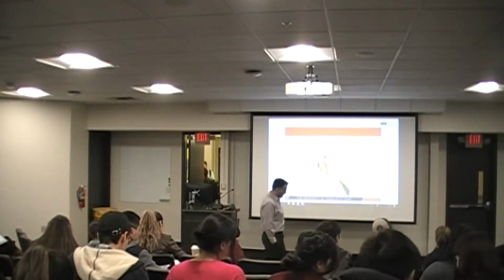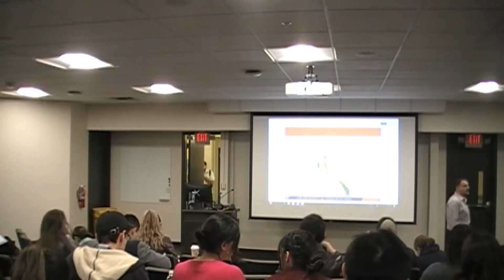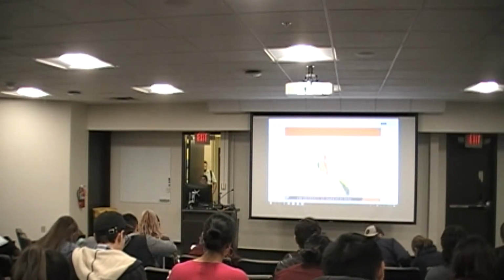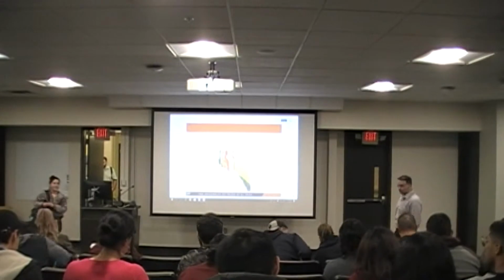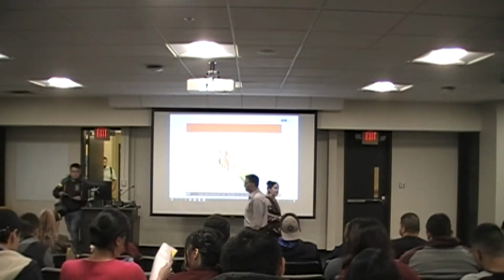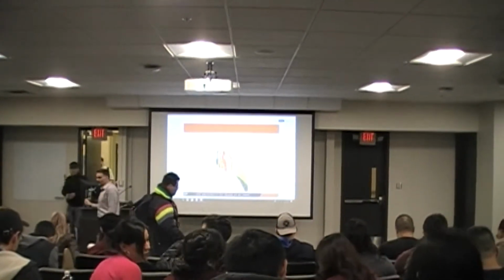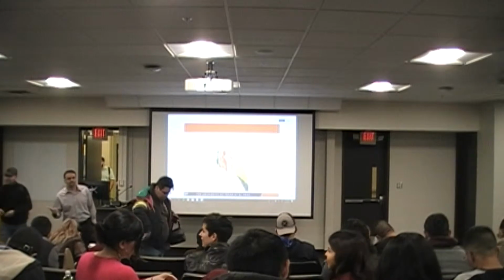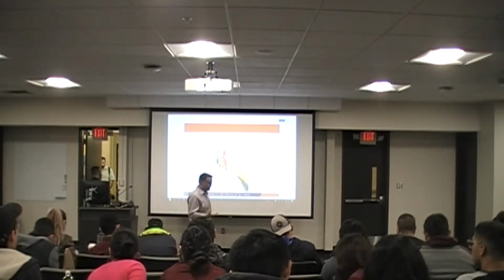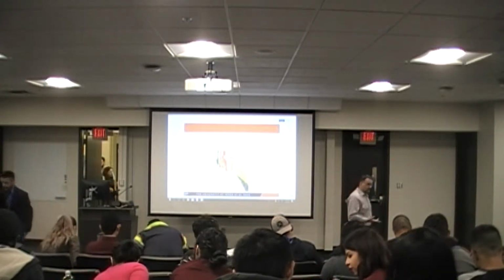We want to figure out how we can systematically categorize the soils into groups with similar behavior. Right? So that's ultimately the objective that we're pursuing. We talked about what we mean by the mechanical behavior. For the mechanical behavior, the things that come to mind are the stiffness properties. Right? What else? Hydraulic conductivity of the soil, permanent deformation potential of the soil, moisture susceptibility of the soil.